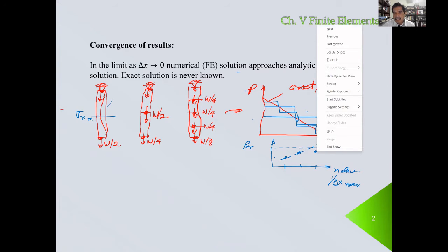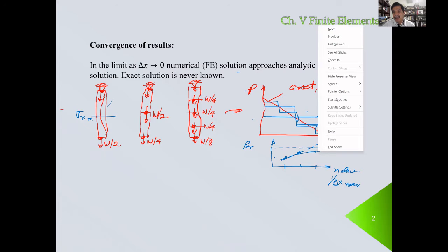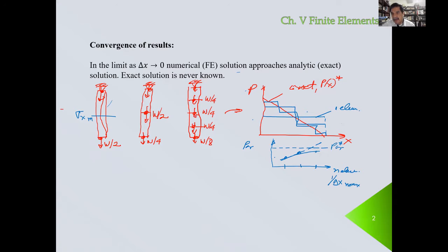Then you immediately see that there is a curvature here. And the curvature here is showing you that you are getting flatter and flatter. And as you go on, you can assume that you are very close to the exact solution, even though this value you never know. So this is the best way that we can do in order to check our results, our convergence. This is something that we have done in previous projects. Always think about that.